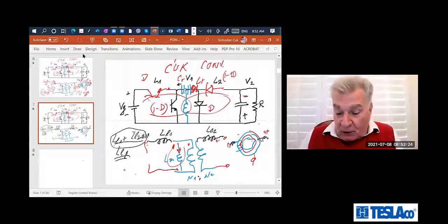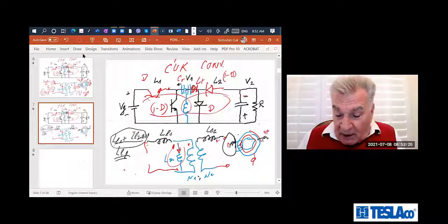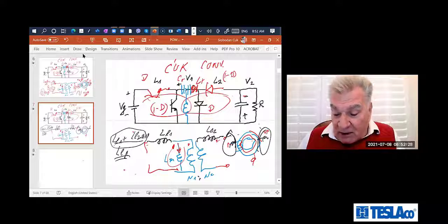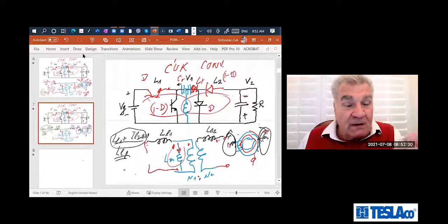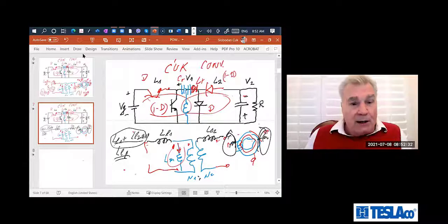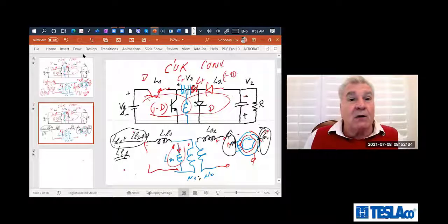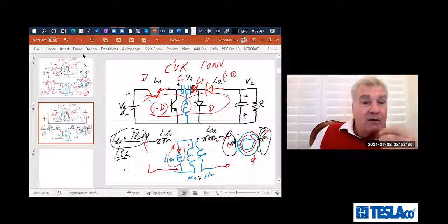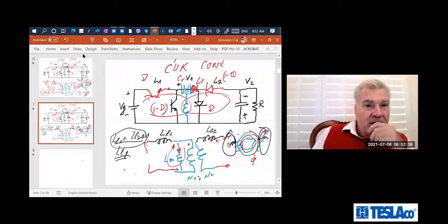So you have a leakage flux on the primary winding and a leakage section of the secondary. That's a true physical fact. But why didn't they care about this distribution? They only cared for the sum of these two, the reflected sum on the primary side.